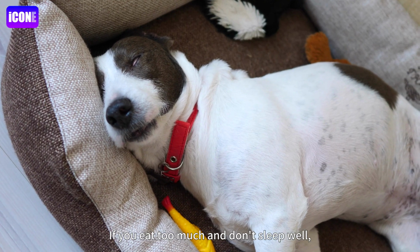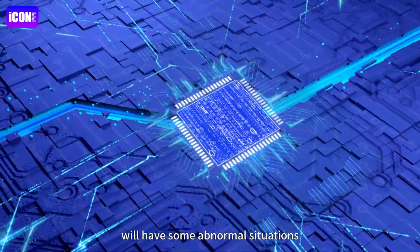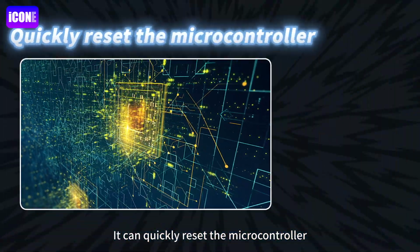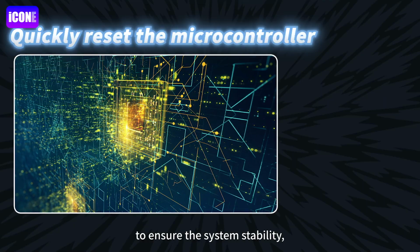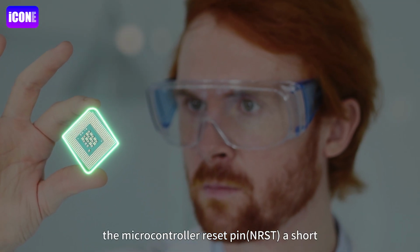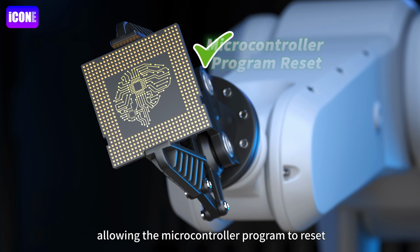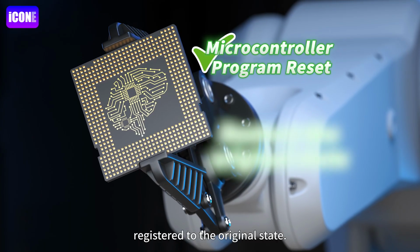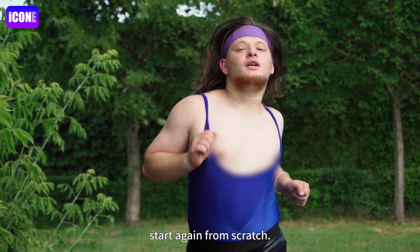If you eat too much and don't sleep well, you will have physical problems. The microcontroller will have some abnormal situations from time to time. So, at this time, a reset circuit is needed to help. It can quickly reset the microcontroller and return it to the initial state to ensure the system's stability and reliability. Its working logic is to give the microcontroller reset pin, NRST, a short low level when the board is powered on, allowing the microcontroller program to reset and restore the state of all registers except the backup area register to the original state. Frankly speaking, it is to let the microcontroller start again from scratch.